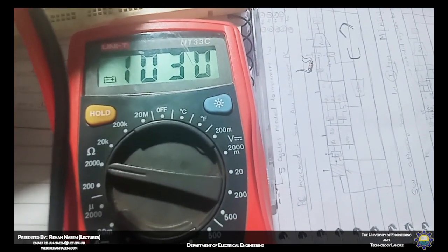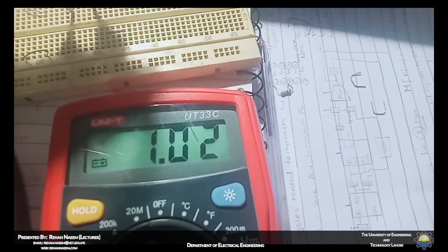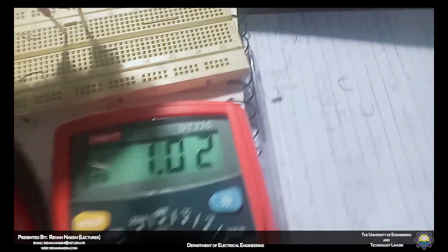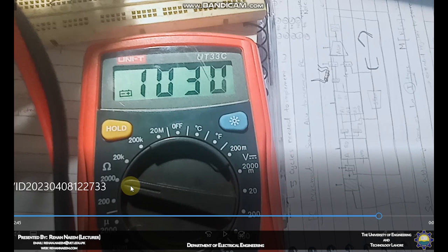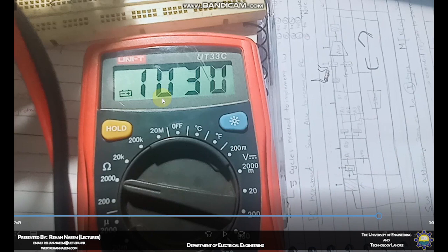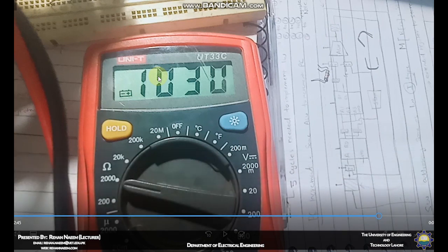तो से फॉर एग्जांपल अगर मैं नॉब को 20K पे सेट करता हूँ, ये आप देख सकते हैं कि आप 20K के ऊपर ये नॉब सेट हो चुका है. तो यहाँ पे देखें वैल्यू आ रही है 1.02. सो दिस इज़ नॉट 1.02 ओहम्स, इट इज़ 1.02 किलो ओहम्स. ओके, से फॉर एग्जांपल अगर ये जो नॉब है इसको यहाँ पे प्लेस किया जाए तो डिस्प्ले के ऊपर आने वाली रीडिंग को मल्टीप्लाई किया जाना चाहिए 10⁻⁶ के साथ. सो कैपिटल M का मतलब है 10⁻⁶. अगर नॉब यहाँ पे हो तो यहाँ पे डिस्प्ले होने वाली रीडिंग को 10⁻³ के साथ मल्टीप्लाई करनी है. और अगर नॉब यहाँ पे प्लेस हो या यहाँ पे प्लेस हो तो डिस्प्ले होने वाली रीडिंग को किसी भी नंबर के साथ मल्टीप्लाई करने की ज़रूरत नहीं है.